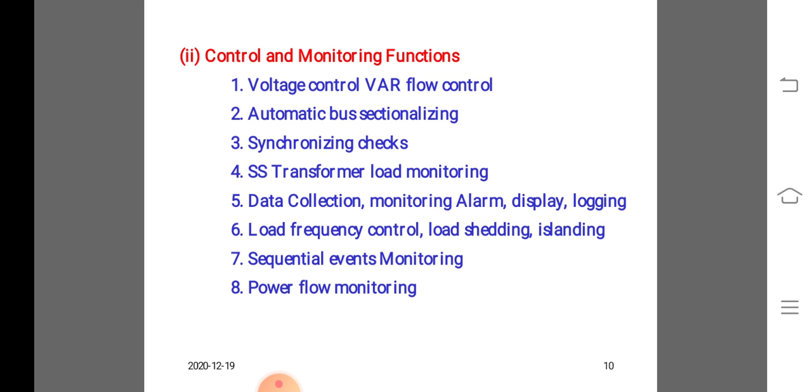Then power line carrier, called PLC, offers an inexpensive and typically more reliable alternative to leased wire. Here the transmission circuit itself is used to modulate a communication signal at a frequency much greater than the 60 Hz power frequency. Most power line carrier occurs at a frequency in the range of 30 to 500 kHz. The security of PLC is very high since the communication equipment is located inside the substation. One disadvantage of PLC is that